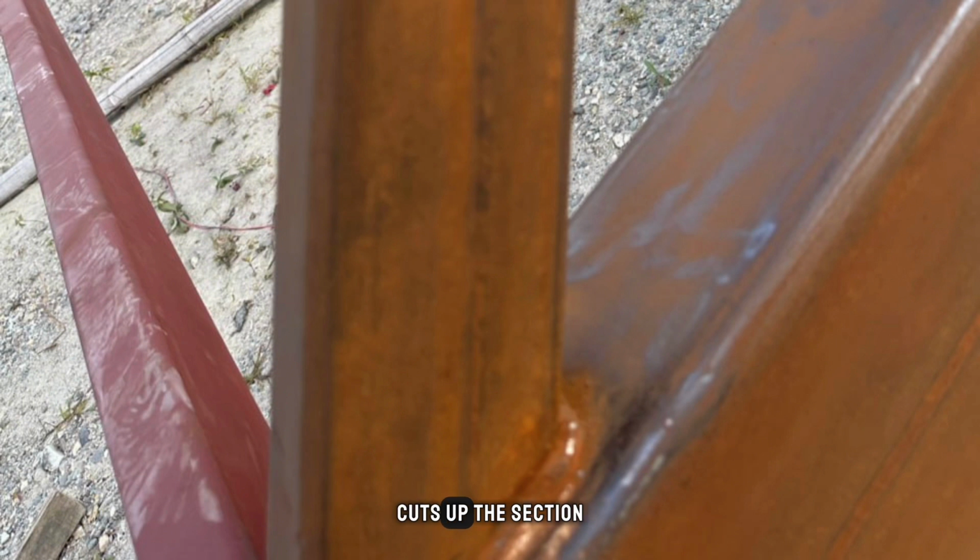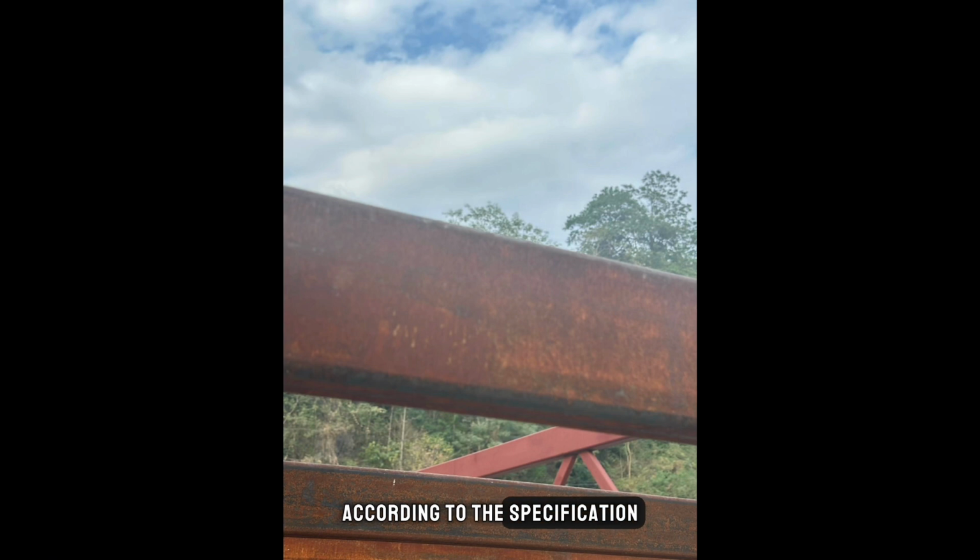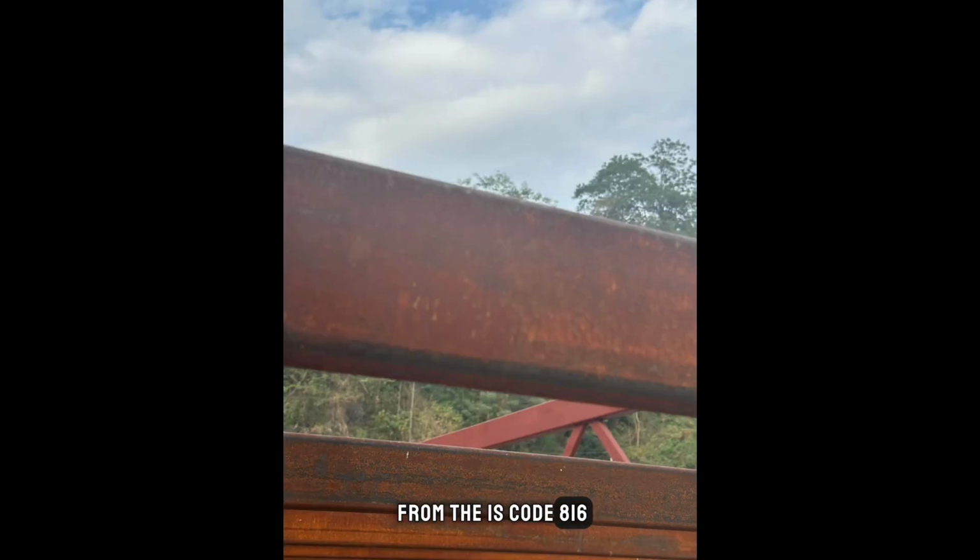Arc welding is the most preferable when it comes to steel. Gas welding cuts up the section of the steel in the process, which affects the quality of steel, unlike arc welding. Arc welding involves creating an arc between the electrode and the workpiece. The heat generated by the arc melts the electrode and the piece together. The spacing, thickness, and the type of weld are all according to the specification from IS Code 816.